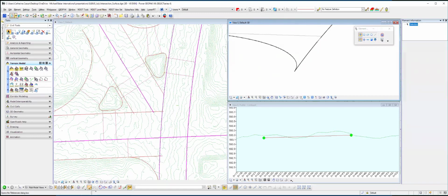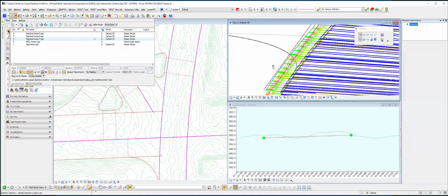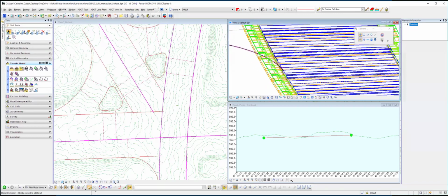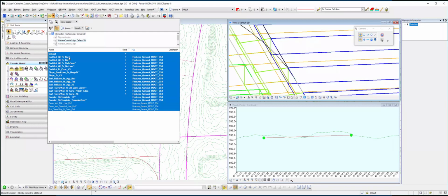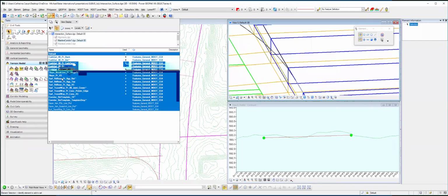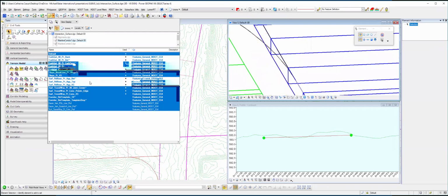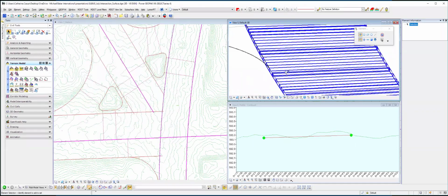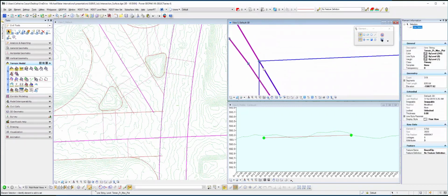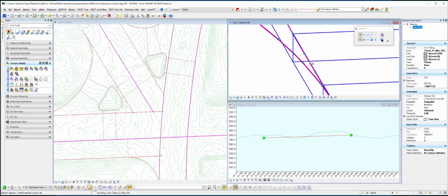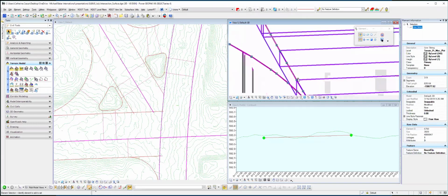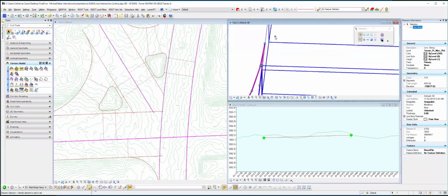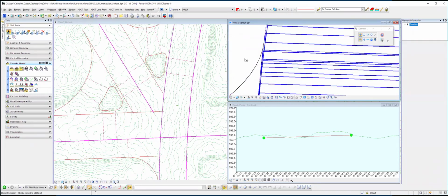So in the case of that other corridor model, if I load up corridor 1, if I was trying to bring these together, not the curb, I didn't take the time to clean up all that curbing and everything, but if you were to take that off, and I was trying to bring these together, I could basically make sure that my clip boundary was connecting to my model, and if it isn't, I can physically move those points and connect them directly to the model, which is really, really handy to make sure that your seam is connected and coming together. You can just pick them up and move them, any of these points.